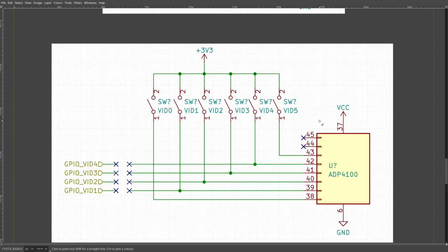And you can boot cards at higher voltages than their typical boot voltage. It is not an issue as long as your cooling is good. And again, we're talking about overclocking here, and competitive overclocking, we can provide that. It's not a big deal. So basically what we want to look at here is how I have all of these switches that connect the vid pins up to 3.3 volts. Now, the important part about that is that by default, remember, there are pull downs. So by default, these are a logic low at about 0 volts.